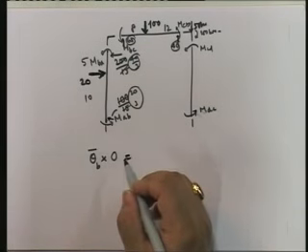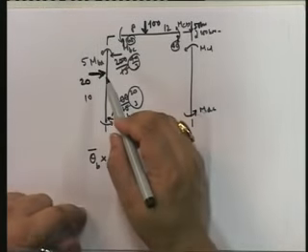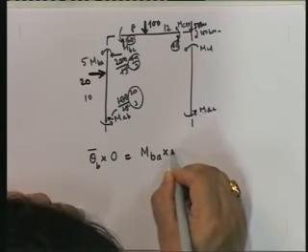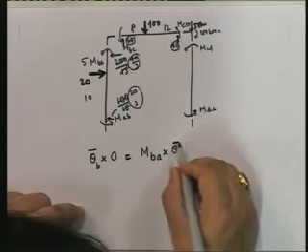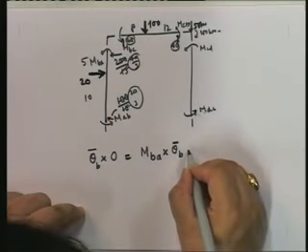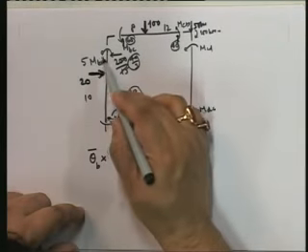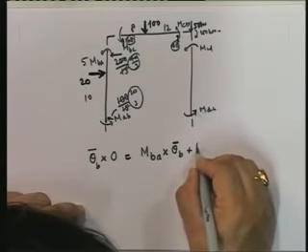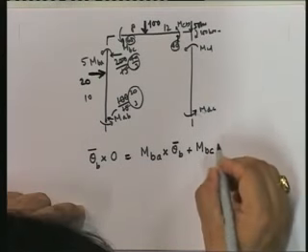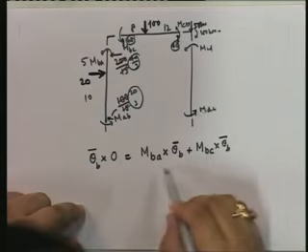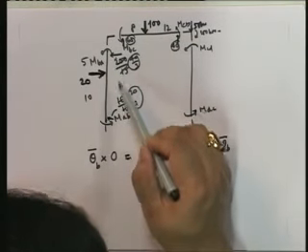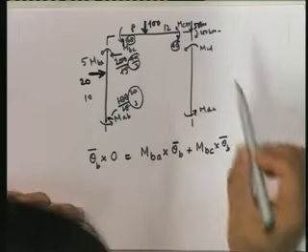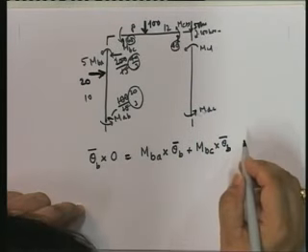And what is the internal virtual work? MBA does work. So it's going to be MBA into theta b, because it's 1 into theta b. Note that the moment is this way, the rotation is this way, so it's positive work. Then plus what else? You will have MBC into theta b. Let's look at all the work done by this and this. These don't undergo any displacements, neither do those, and neither does that. So this is my equation.